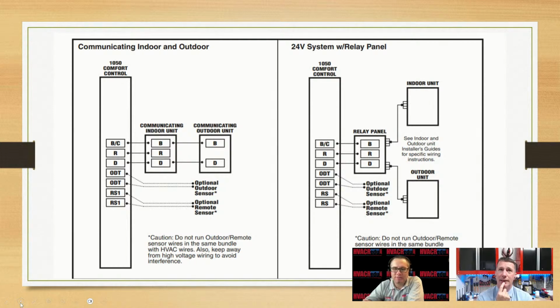So what's our communication? B and D, process of elimination. So we're using B and D for our communicating wires. What's interesting is that remember we had 4 before on a lot of these manufacturers, and this one only has 3. But notice what B has next to it. B's got a common.